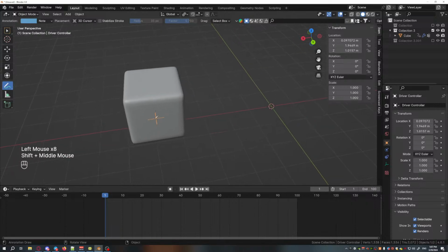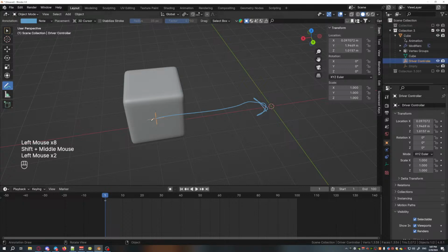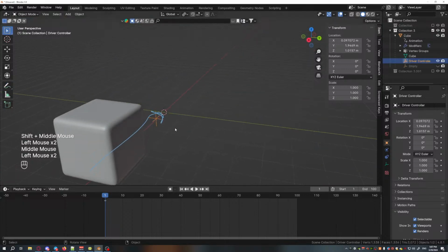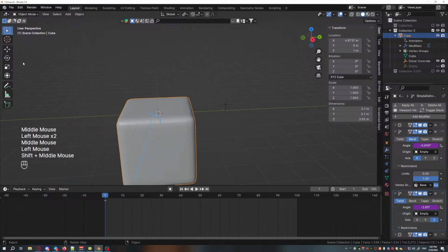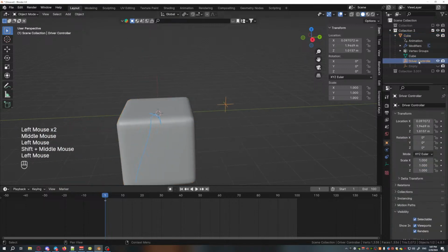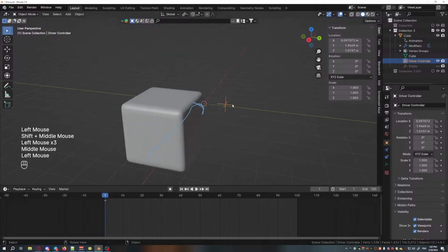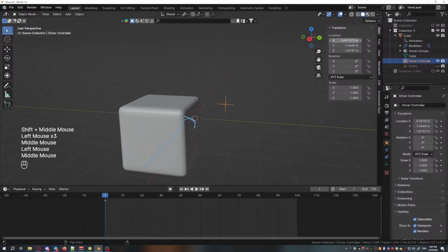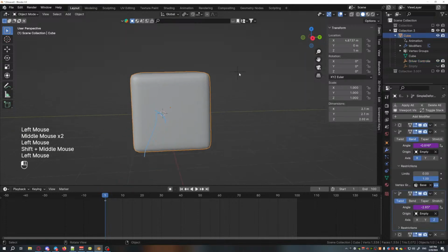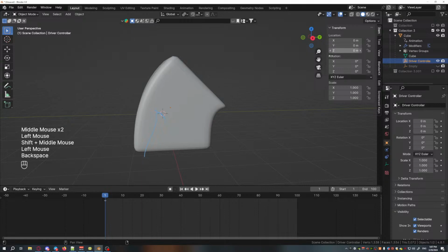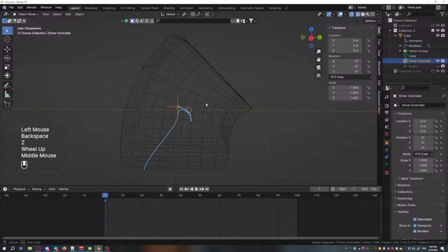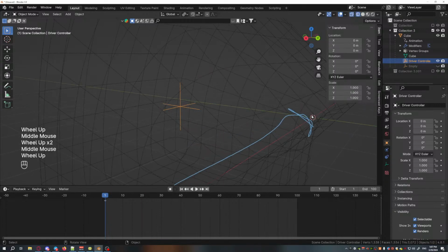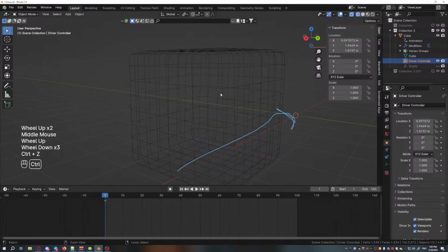It can be either relative to the world, or if you properly parent your object, like this empty is now parented to the cube, as you can see, it is now in the subfolder of the cube, then its local coordinates are calculated from the origin of the cube. So if I reset this to 0, you can see that it goes to the 0, not of the world, but of the parent object.